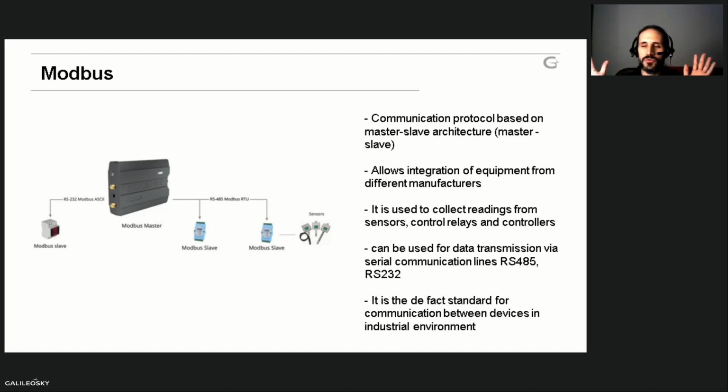It allows you to integrate equipment from different manufacturers. It works on a master-slave architecture, so you have one master device that creates requests and sends them to the bus. The device that is requested by the master will answer, and the others will just listen and stay quiet, right?